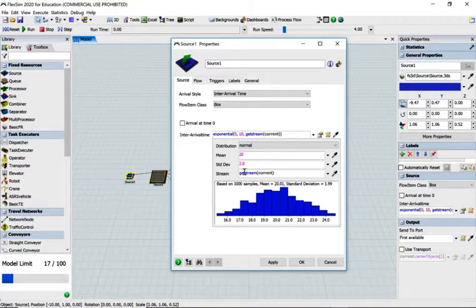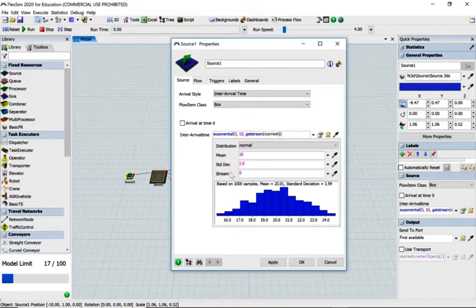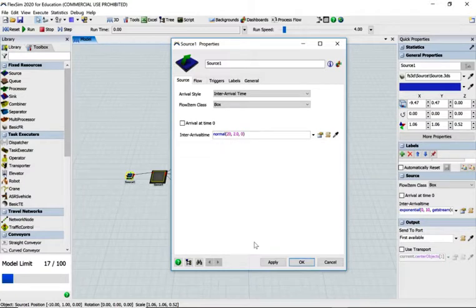What the stream is, it's a way the computer generates random numbers. On older versions, you might be asked to type in the number 0. It's fine to do that here, but I tend to leave it. It doesn't really make much difference, especially in the models we're going to be creating. If you're going to create a massive model, then you might want to change this number yourself on different objects to create a little bit more randomness. So let's click down there and click on apply.